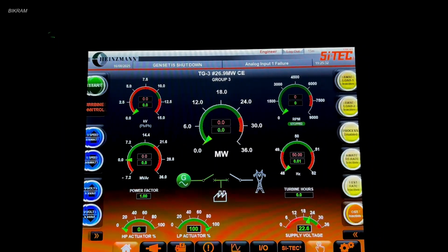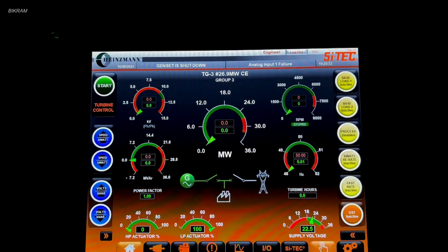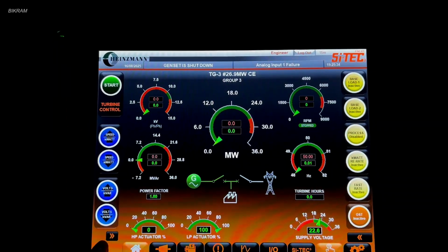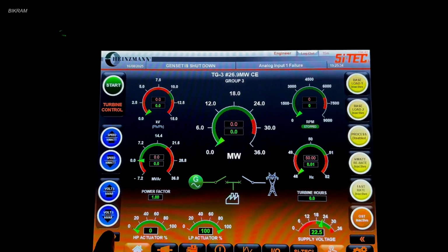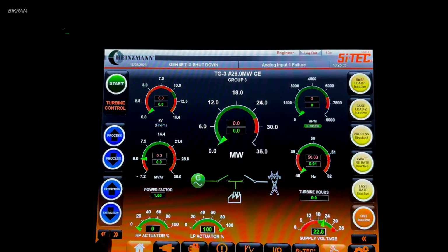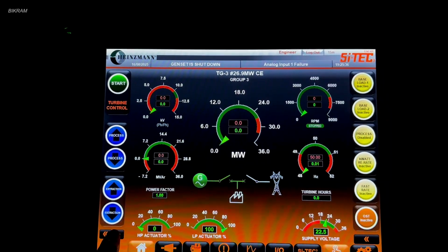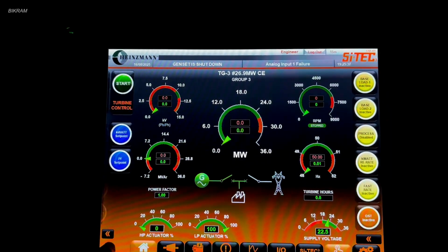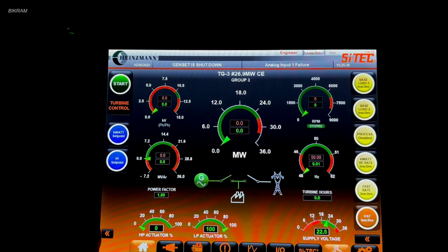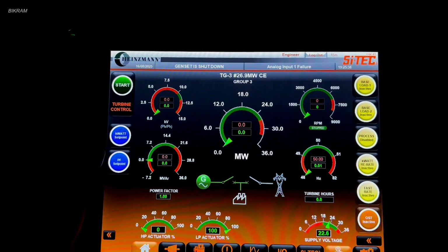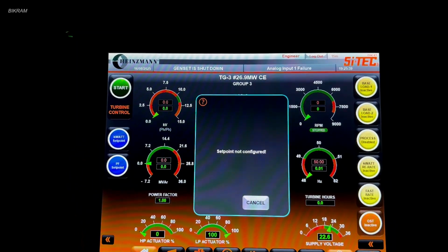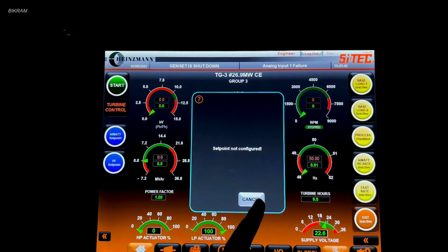And if you check, there is a finger picture on the bottom side. Once you press that, some soft switches pop out from both sides. These are actually the control switches or soft switches. With the help of these switches you can switch on or off certain things like process enable, disable, and base load control enable, disable. You can give a set point of VFs and kilowatt also. You can start your turbine from here also. And the kilowatt is not configured.